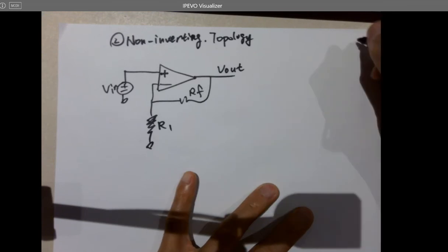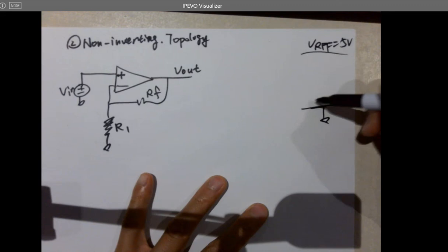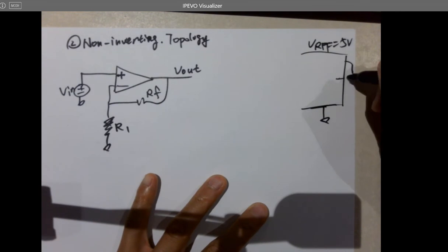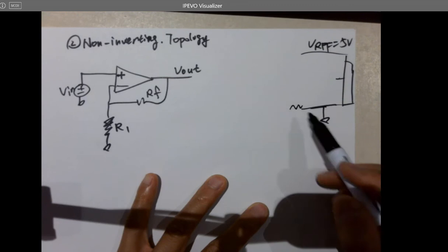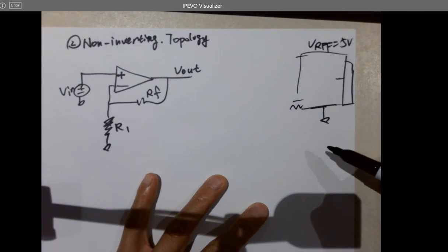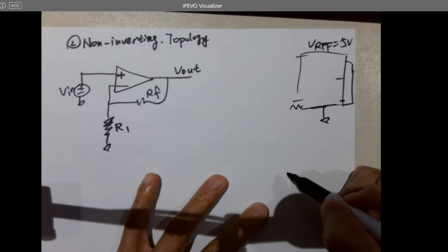So for example, your ADC is like Vref equals 5 volts and ground, right? You can resolve this entire range. You can resolve the entire range for the ADC. It's like an input for the ADC. And your swing of the analog signal is like this. You are wasting all the range. So your little step is probably the full range of the input. So you cannot resolve anything.